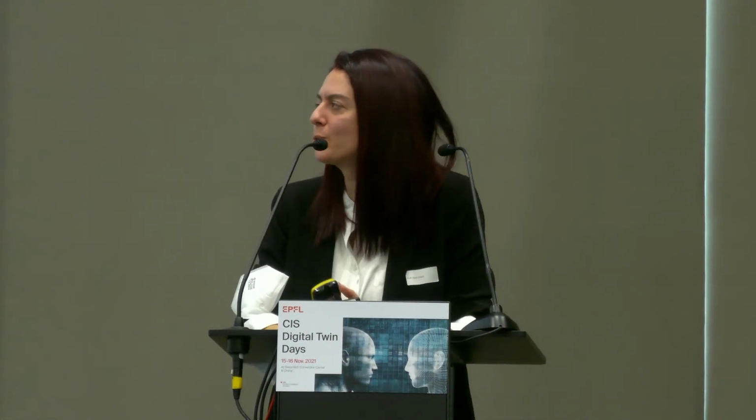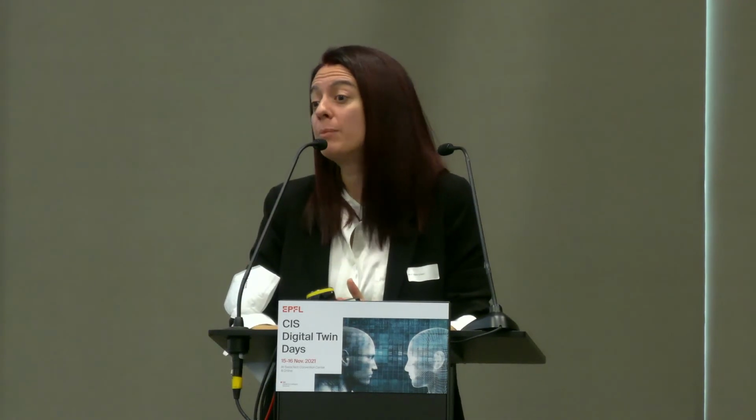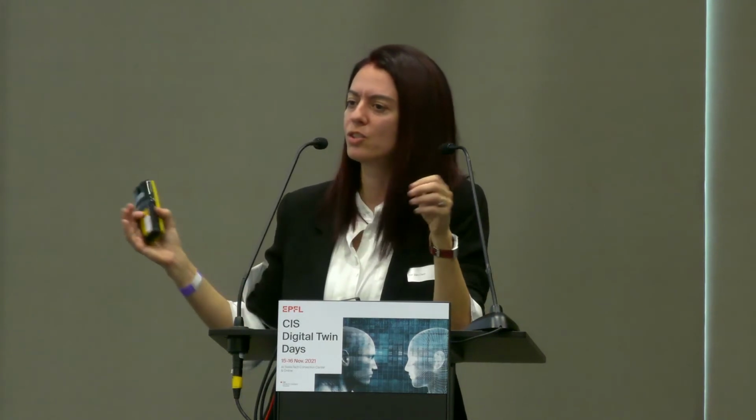Well, actually, this is a great question, and if you're going to give me more sensors, I'm not going to say no. And what you're describing is what we call distributed sensing. So there are skins that you can use. There are fiber optics that we use as well. You can cover kilometers of a bridge deck using a fiber optic system, and that's an even better situation. But even then, typically you cannot promise to cover the whole structure using these sensors, which is why we suggest using this.